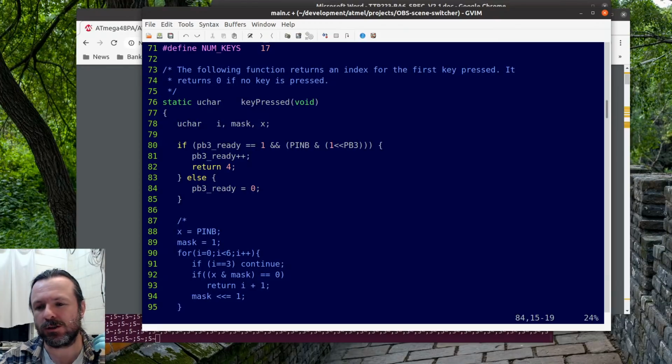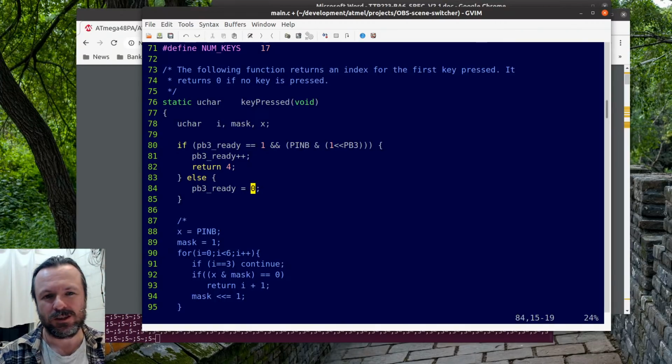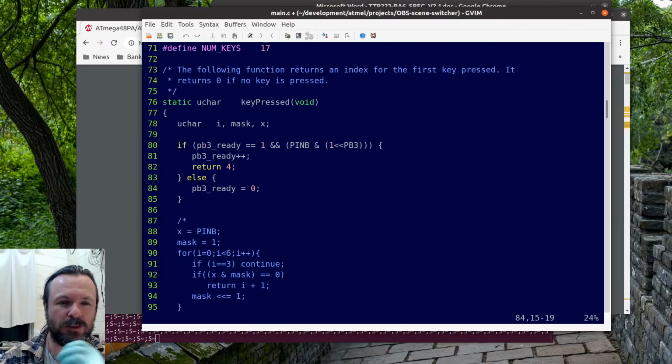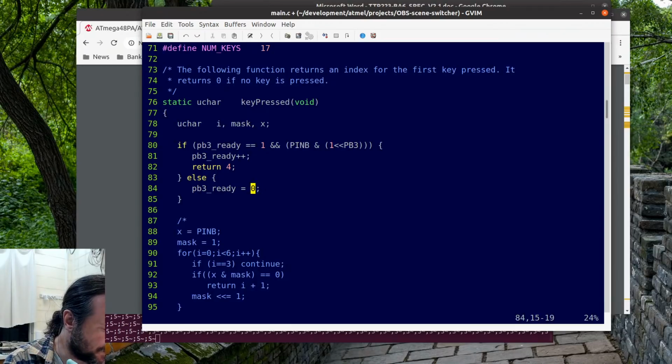Yeah, Tom George, the trouble is, to do leading edge detect, I have to do it through the interrupt system, and to do that may interfere with the USB timing sequences. So that's why I'm not doing it through edge detect. I can do it, but it will probably mess up the USB sequence. So we're basically having to do something similar, but it has to be through software. Well, I'm wondering though why it's even having this issue in the first place. We've got a pull down resistor there and everything, and it's still somehow managing to pull up. Or drift up, rather.